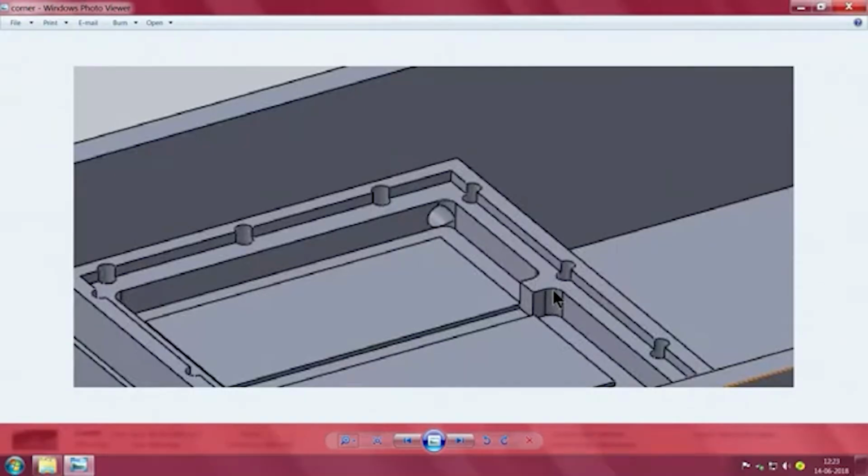The corresponding thing what we need to make in the heat sink, we have to make all this funny stuff. Instead, it has been just machined through using probably a 6 mm or an 8 mm end mill. The whole thing has been machined through. The same end mill is run here, and to make multiple parts, the same G code file which is used now can be used here, so that the whole thing can be machined directly using a CNC machine.